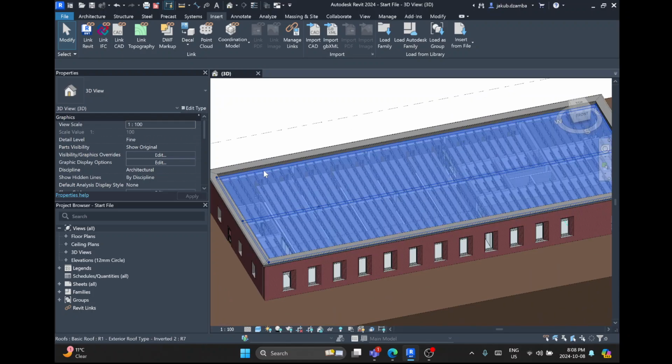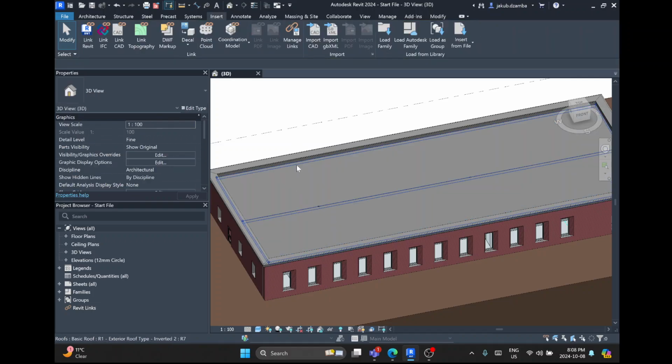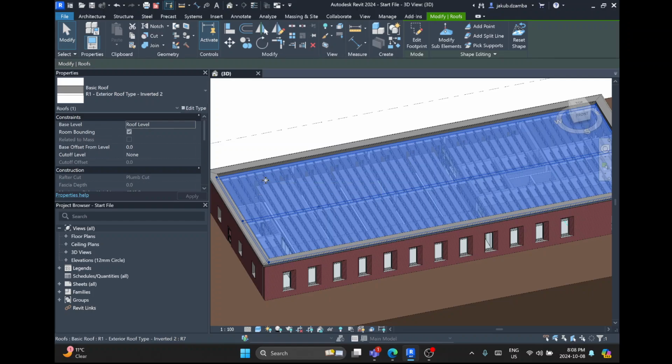The way it's done now is fine. It actually makes a lot of sense because the easiest way to create a slope towards the middle of the roof is to slope the joists by 2%, and then you end up with a sloped roof exactly the way Michael drew it. The second easiest way, and they're sometimes comparable, you can interchange them, is to basically make all the joists level, and then you work with the insulation manufacturer, you send them a drawing of your roof, and they will send you a bunch of numbered insulation panels that, when you install them correctly, create a slope to every single drain.